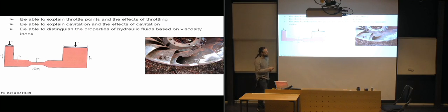and this generates the bubbles. So what might have happened in this situation, for an example, is that if we have a small damage to the side of this blade, it's going to create bubbles in this area, but it's also going to let bubbles fly past it and over to this wheel. And that's probably why this wheel is really damaged, because it's been in the stream of bubbles coming from this one. So you can get sort of a piling on of damage effects with the cavitation.